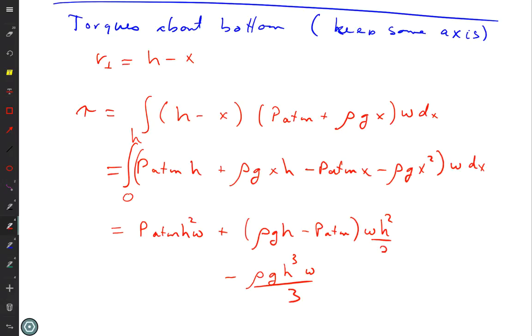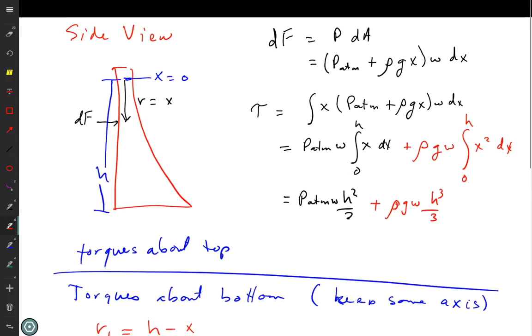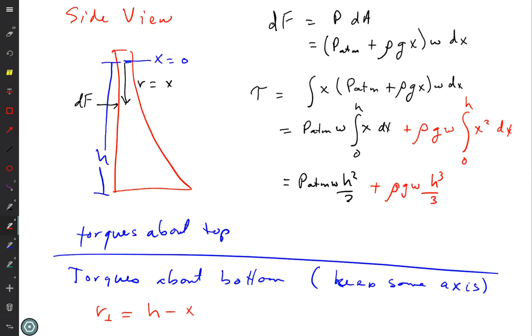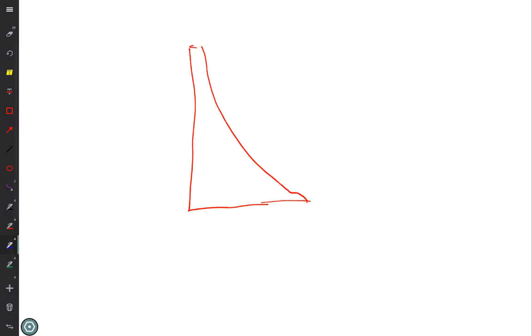Can you show the torque one more time for the force of gravity and for the other mass that you were showing on the dam? Okay. So torque's about, let's say about what location first? The top. Okay. So torque's about the top. I'll just go to another page and draw forces on this, and then we'll calculate the torques from each one, just direction.